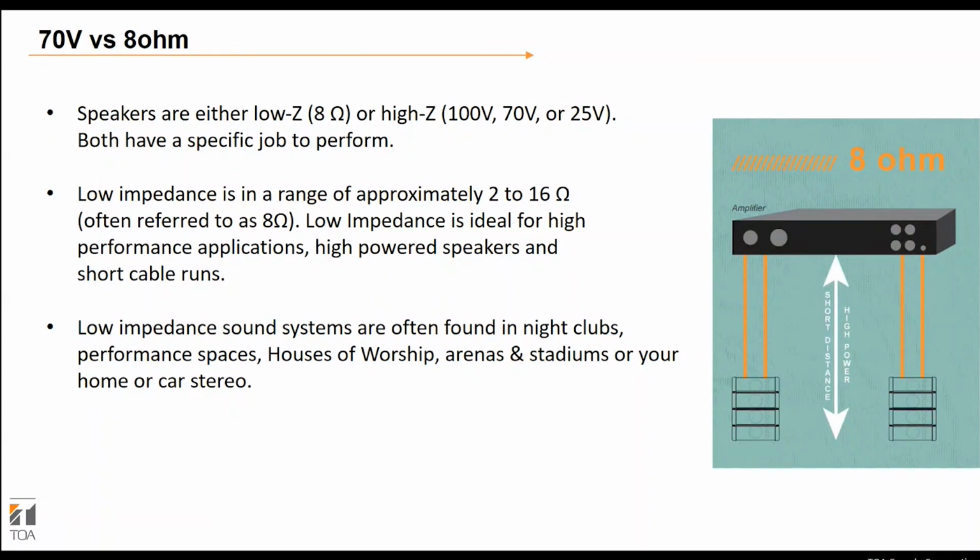Low impedance generally is ideal for higher performance applications where higher powered speakers are in use, and with shorter cable runs, because you do have a lot more signal loss on a low impedance run than you would on a high impedance run. So typically you really have shorter runs for the low impedance speakers. Also, things like RF interference can become an issue for longer runs on low impedance cable.